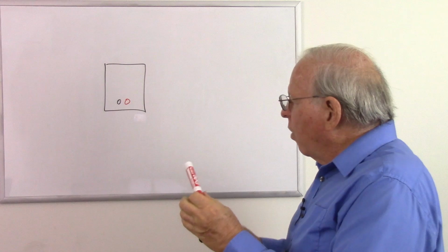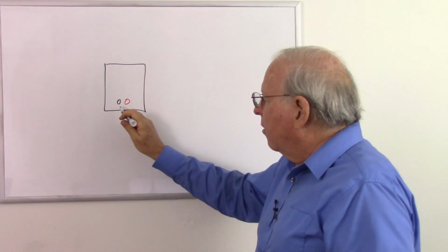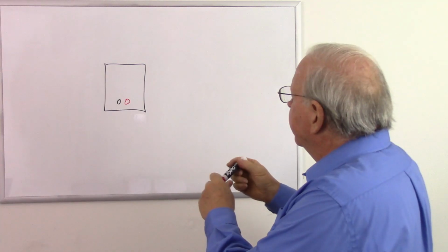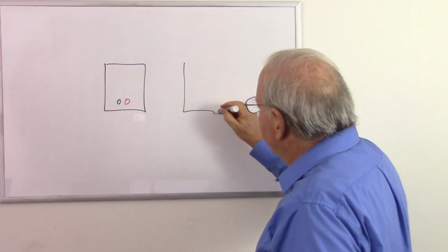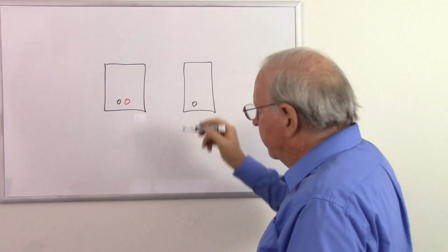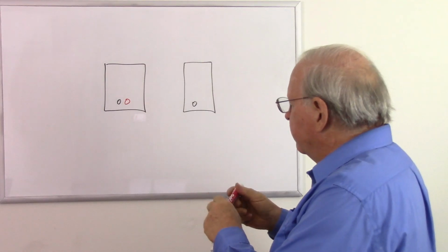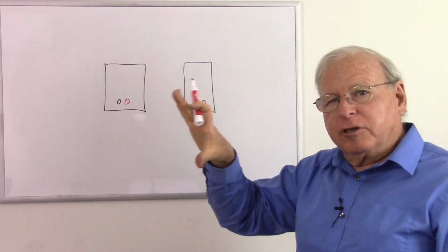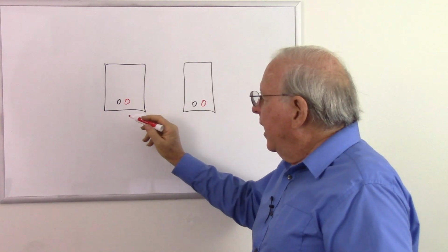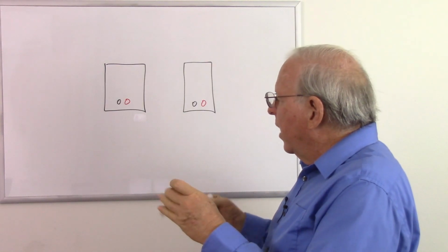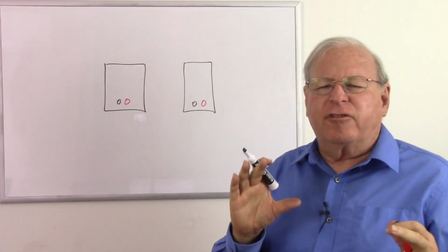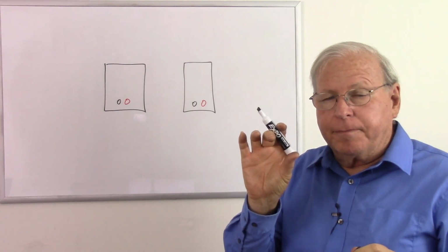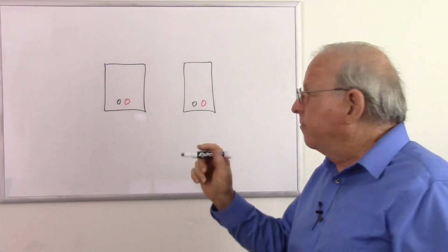And your wires, make sure that your wires are the same for both speakers. Let me draw another speaker over here. So here are your speakers. There's your black input. Here's your red input. It might be screw terminals, might be push terminals, whatever it is. And we want to have our wiring going the same. So there'll be some indication as to which wire is which. Is there a ground? No, there's just a positive and negative basically.